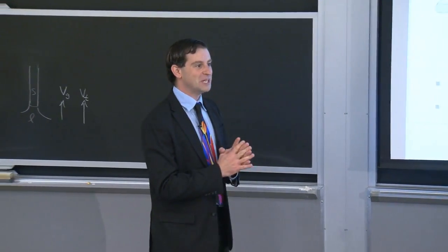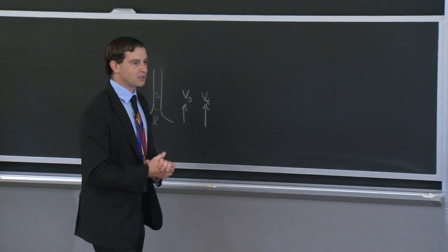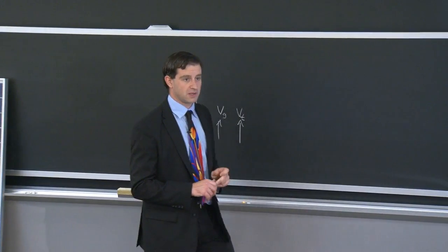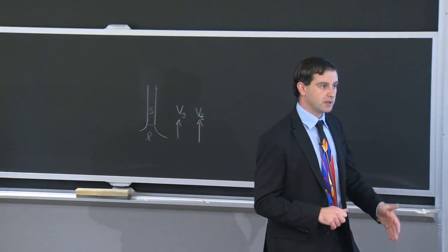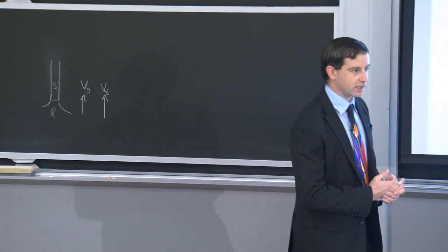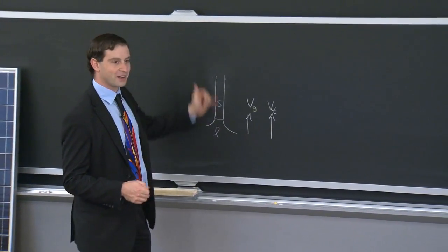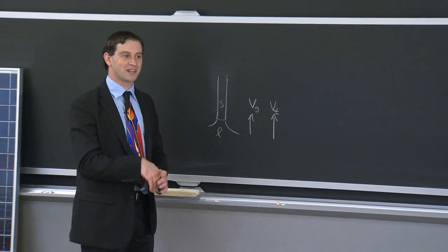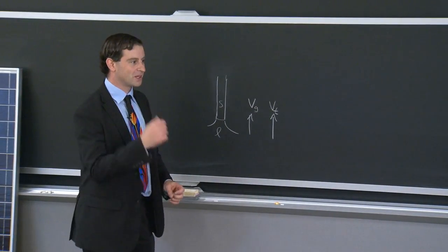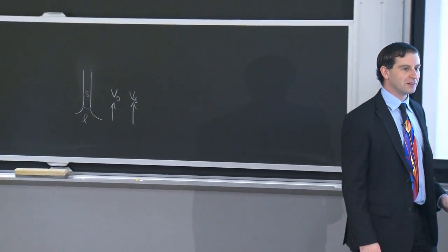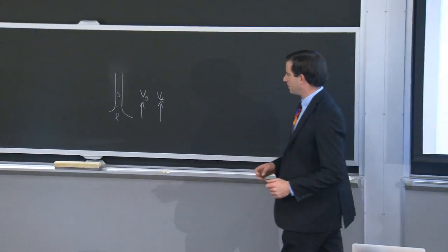You can use your imagination. But ultimately, growth continues in air, and you're limited to, at most, around 5 centimeters per minute growth velocity because of the extraction of latent heat. If you try to grow faster than that, you'll eventually just pull the solid off of the liquid. It'll dissociate, much like pulling an ice cube off of the top of a glass of water. Right? Surface tension won't be able to hold the two together.